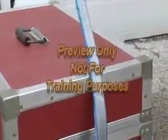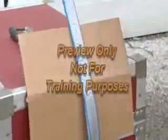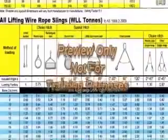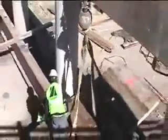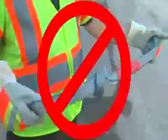Before placing a sling, you should always pad sharp edges on the load with material of sufficient strength to protect the sling. Slings should only be shortened or adjusted by methods approved by the sling manufacturer or a qualified person. Make sure slings are not constricted, bunched, or pinched by the load, hook, or any fitting. Never shorten or lengthen a sling by knotting or twisting.